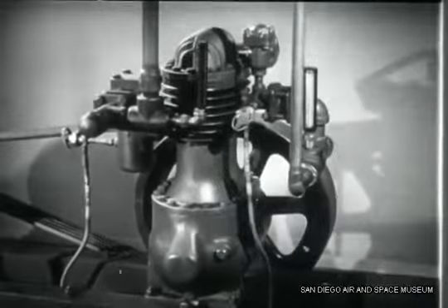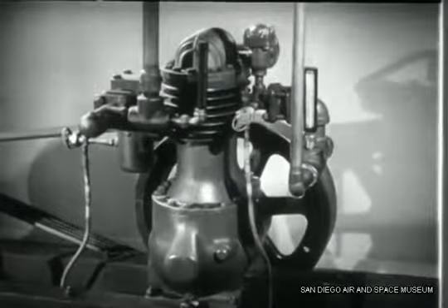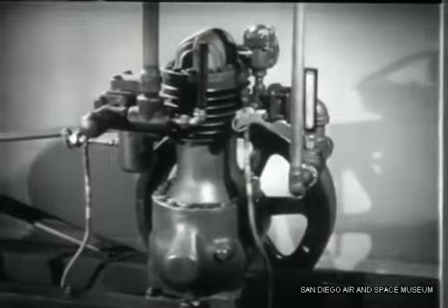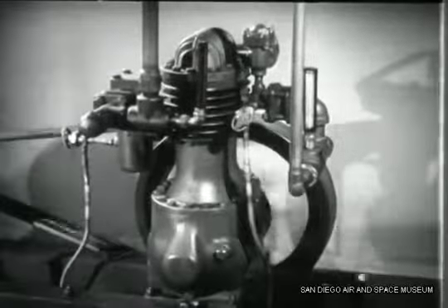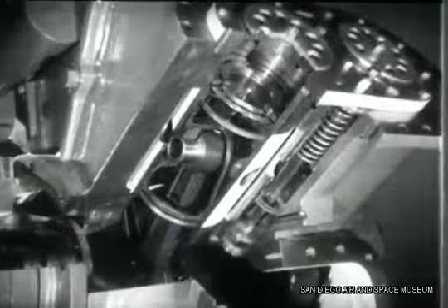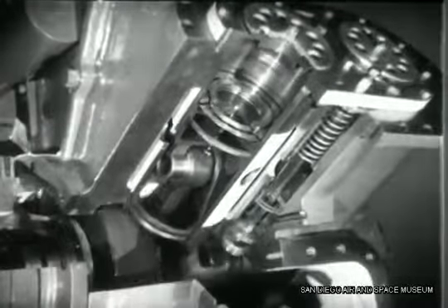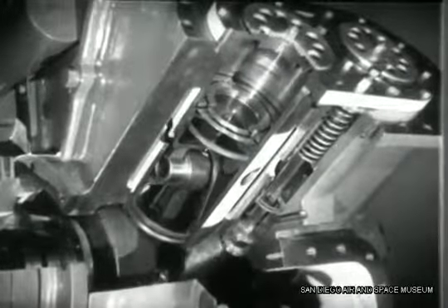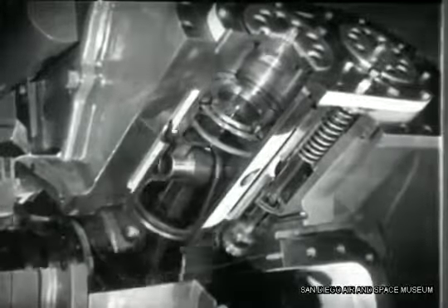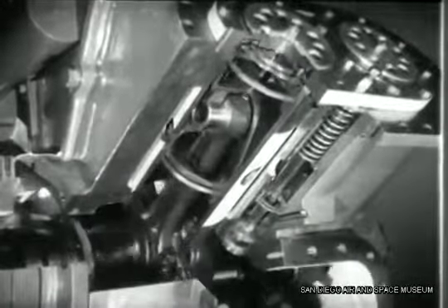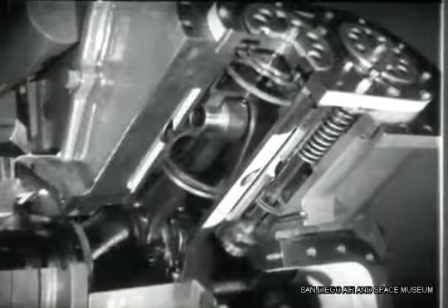Here is the compressor, which acts much like a pump. It really has 2 jobs. It raises the pressure of the refrigerant gas, as we've seen, and in addition, it keeps the refrigerant circulating through the system. The inside of the compressor looks something like the inside of an automobile engine. It has cylinders, pistons, valves, connecting rods, and a crankshaft. An electric motor drives the compressor crankshaft. Usually, 2 or more cylinders are used for smoother operation and to keep an even flow of the refrigerant gas.